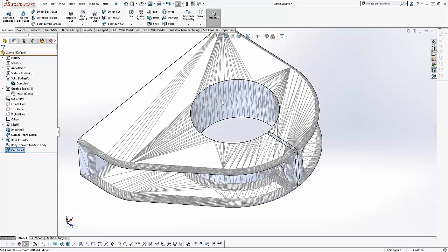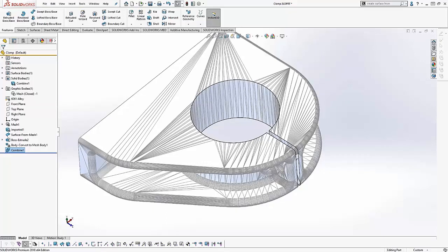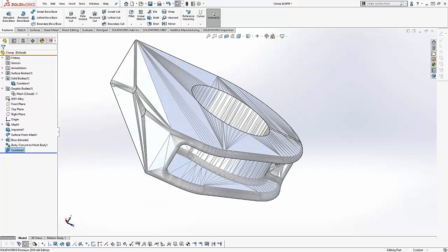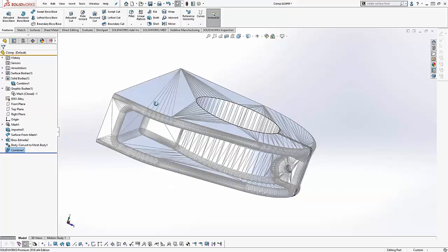Additionally, with the ability of capturing these different surfaces, we're able to export these things to use inside of assemblies, so we can actually use them for mating processes. So now that we have a nice flat face with concentric holes, we could use that inside of an assembly if need be. So just something new for SOLIDWORKS 2018 called mesh bodies.